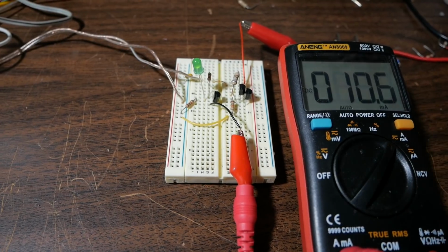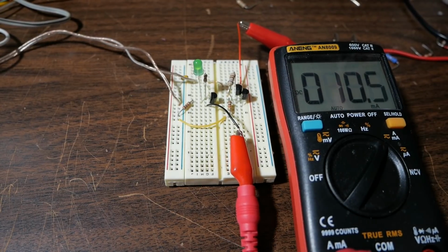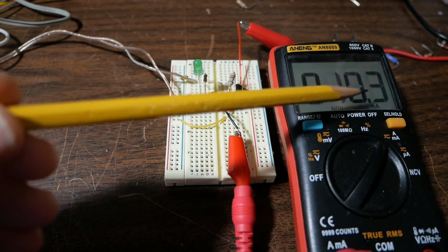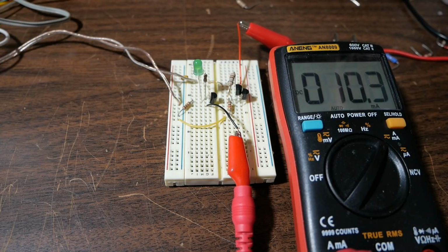Okay, for the first test with the CCS that has the LED, I'm going to vary the voltage going to the base. Now it's set for about 16 volts, and I will drop that down, and it's now about 9 volts or so. You can see it's dropped a little bit. When you change the current across the LED, the voltage drop will change a little bit, which affects the current of the CCS. So keep dropping this.